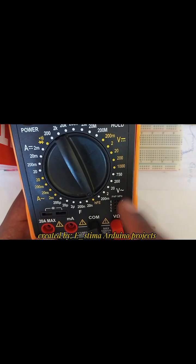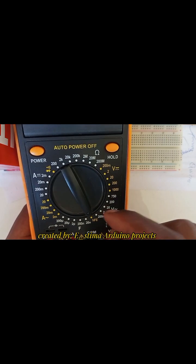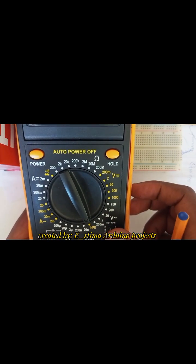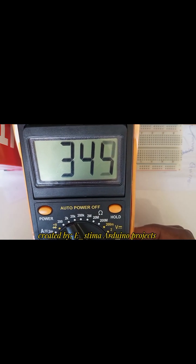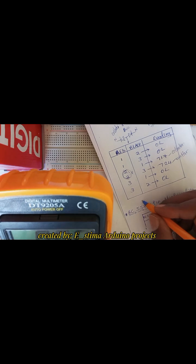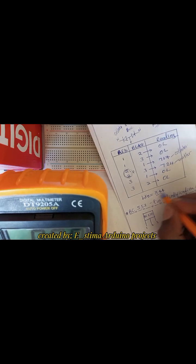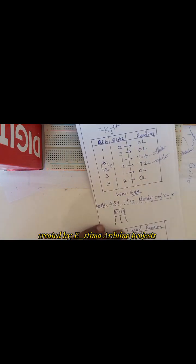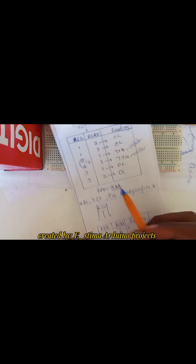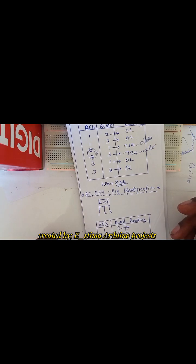So where I have NPN, I'm going to fix my transistor and look at the reading: 344. Then I record here HFE is equal to 344. This is my transistor gain, HFE. Let us go on to the next transistor.